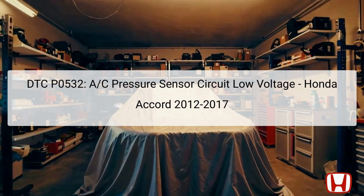The AC pressure sensor is responsible for detecting refrigerant pressure changes, which is essential for the air conditioning system to function efficiently. When the air conditioning load is low, the sensor outputs a low voltage and high voltage during high load. The Powertrain Control Module, PCM, essentially the vehicle's computer, monitors these voltage signals to ensure that refrigerant pressure remains within acceptable limits. If the sensor's output voltage is below a specific threshold for a certain duration, the PCM registers a malfunction and sets this DTC.